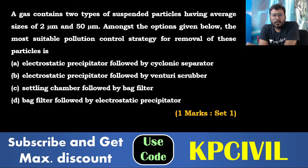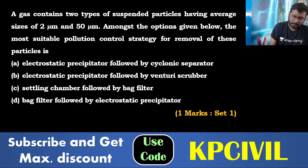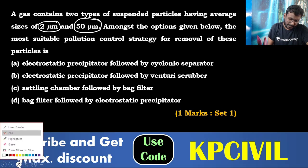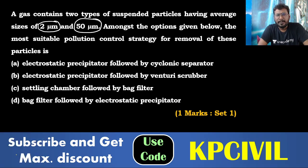A gas contains two types of suspended particles having average sizes of 2 micron and 50 micron. Amongst the options given below, which is the most suitable air pollution control strategy for removal of the particles? For 50 microns, we always go ahead with gravity settling chamber. Equal to or greater than 50 microns, we go for gravity settling chamber. For 2 microns, electrostatic precipitator or fabric filter are options. So we'll check the options.